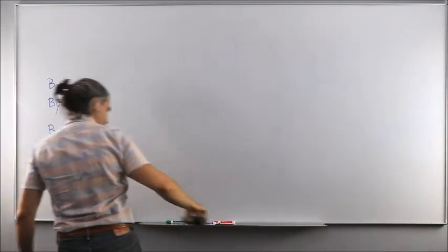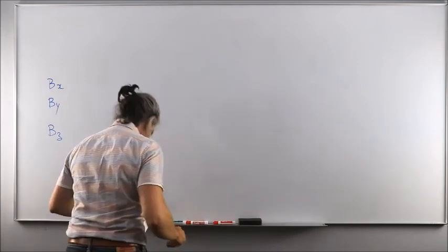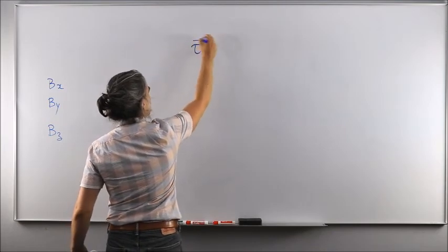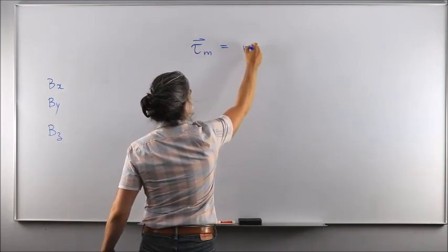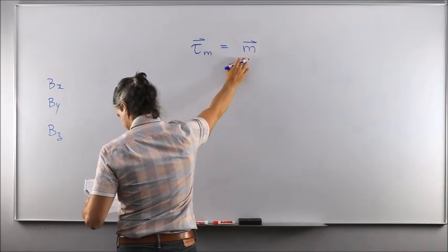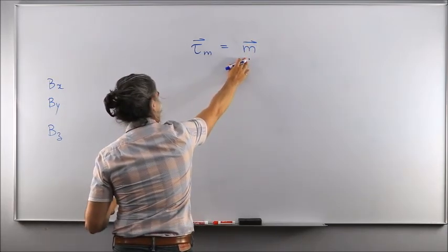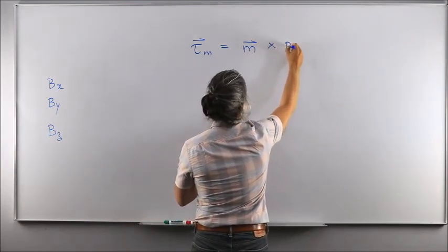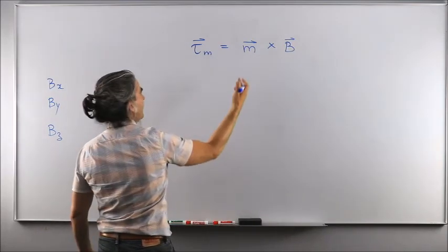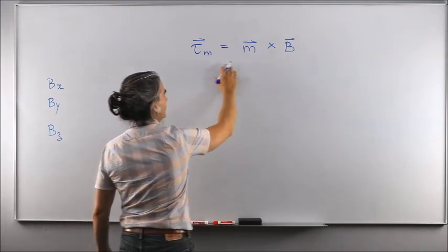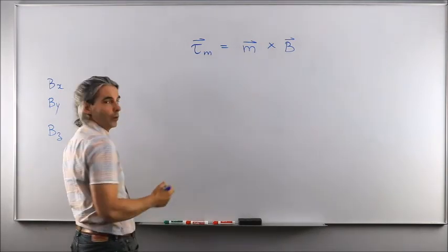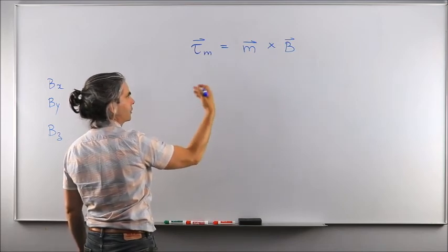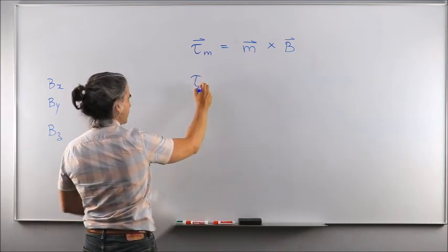And you'll see that it's not that difficult to do because you'll just have to go back to the expression we had for the magnetic torque vector in vector form, which was the magnetic dipole moment of the spacecraft itself due to its current loops, cross product with the magnetic field in terms of vector. Well, in Euler's equation, in order to be able to use that, we need to turn that into components in a body fixed reference frame, which is the reference frame used inherently in Euler's equation of motion.